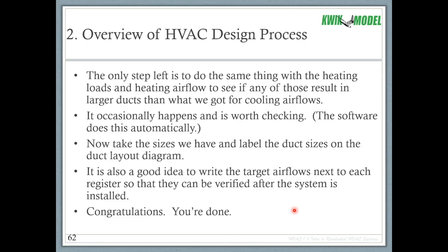Occasionally we'd find one that was low. Most of the time it was caused by an installation issue, a duct being crushed or something like that, or maybe they had to run the duct farther around to get around an obstruction, and so the airflow was a little less than we needed. As long as it wasn't way under the target for that room, and as long as the total airflow for the system was good, we generally almost never had an issue. I don't think we ever did have a comfort complaint, as long as we met that criteria.